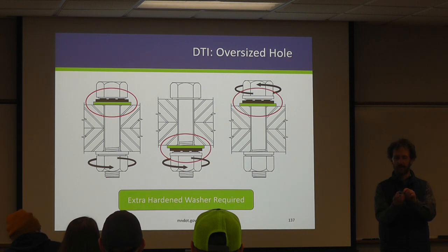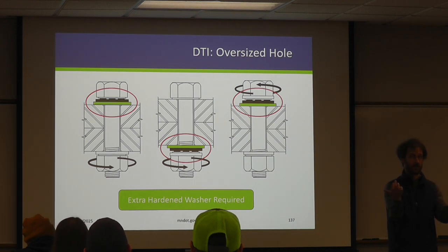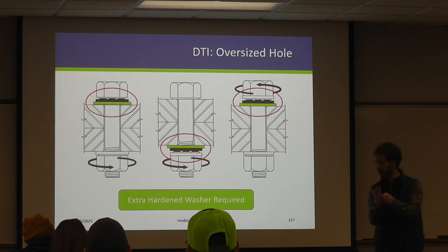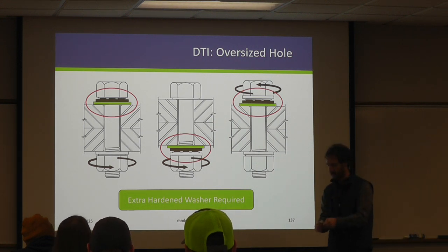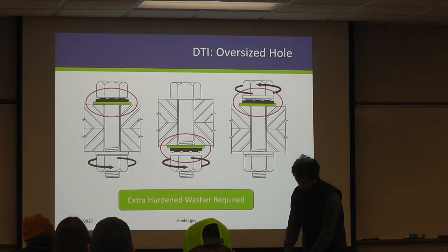What had happened was, because this hole is slightly smaller than the hole in the steel, the DTI sucked into the hole. None of the protrusions were crushed. So you can see the outline of this hole in the steel beam in this DTI. So we had no idea how tight it was. That was partially why. That hardened washer prevents that because it gives it a good strong back. Does that make sense? Again, something you want to check for before they start stuffing holes.